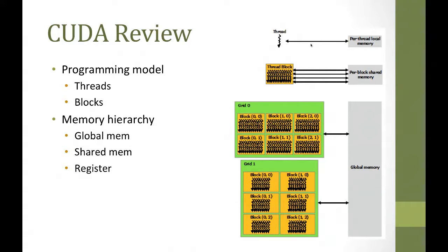And we also have the fastest storage place, called a register. Register can easily achieve something like 7 terabytes per second bandwidth, but it's only visible to each thread. Well, it's not actually only visible to one thread, but for the programmer, it's only visible to the thread. For the hardware, it can be shared with other threads. I will talk about it more later.